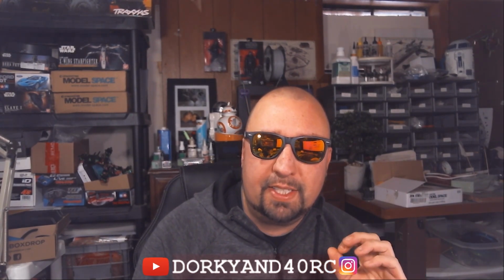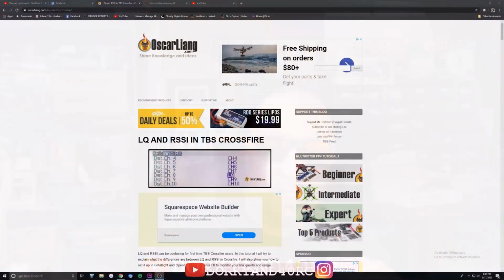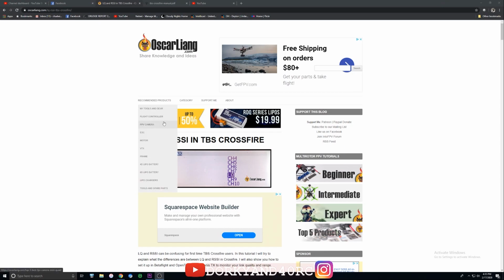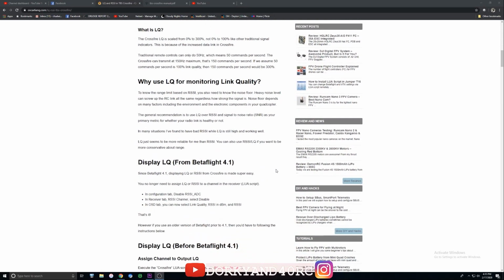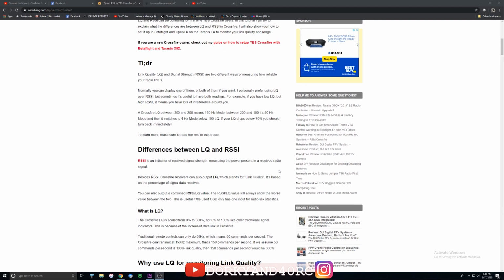And I know a few people have commented about the whole link quality discussion, the scaling 100 to 300 when you're in 150 Hertz mode and when you're in 50 Hertz mode. I would encourage everybody to first of all look at the TBS manual, but the verbiage in there is kind of confusing. I think the best explanation of the whole link quality thing would come from Oscar Liang himself. If you just do a Google search for RSSI TBS Crossfire, he goes down through here and explains everything pretty good when it comes to all that stuff, how to set it up in your Betaflight OSD, which is really important for some people if you're running 4.1 or 4.0.